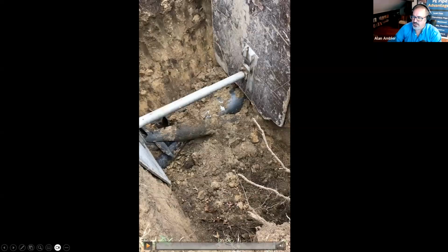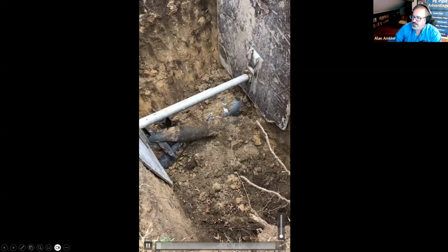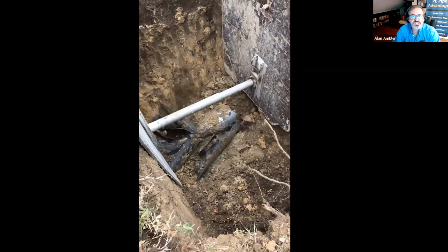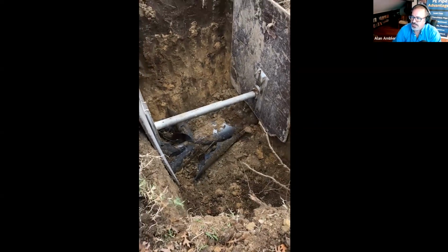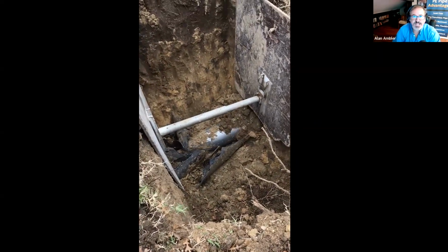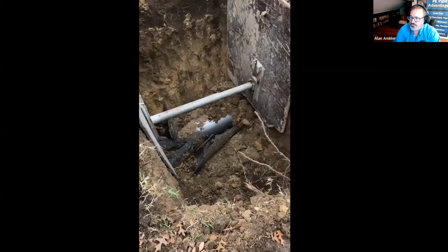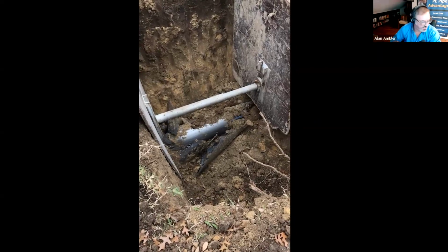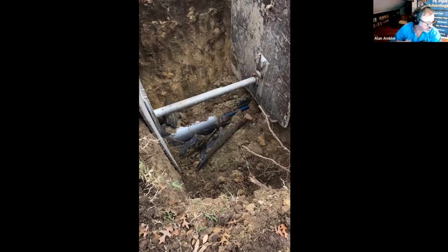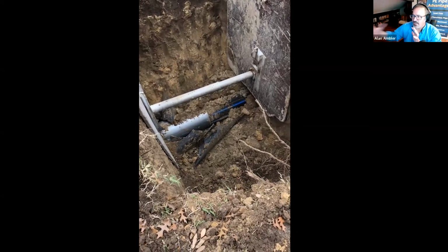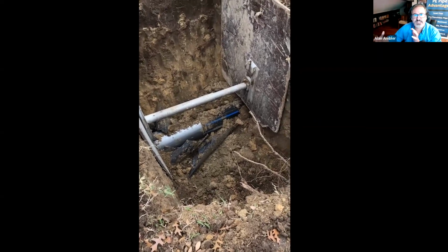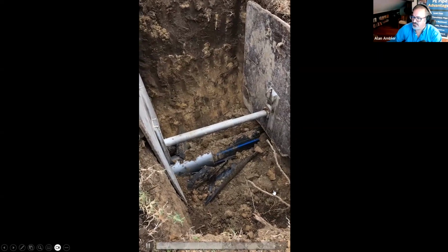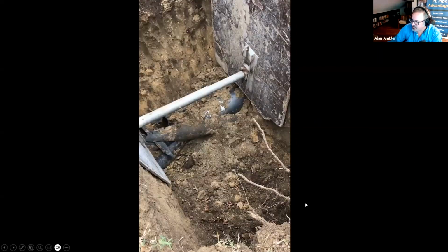So here's a primary example of some cast iron pipe that's being burst. It's been exposed at a service connection or a lateral connection, or some other type of connection to appurtenances or what have you. And then that pipe itself is fractured by the expander head. The expander head is connected to the high density polyethylene pipe in that manner, and it's just really coming through, as you could see through this video. And here's the next one.